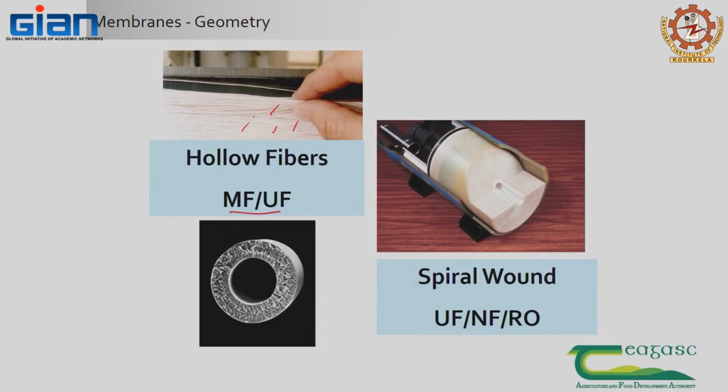Do you think membrane is the best way of filtering substances? Looking at these slides, yes it is. But how many times can you use a specific membrane? Because certain membranes should always be in a solution. It is not like a tea filter, you clean it and tap it and keep it and use it again. Some of the membranes have to be always in a specific solution, because if they dry off they won't work, and their configuration and chemical composition might change.